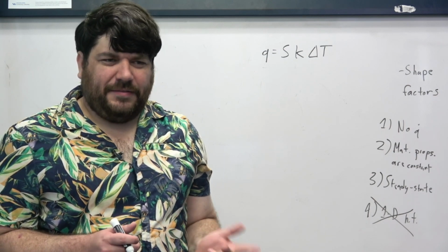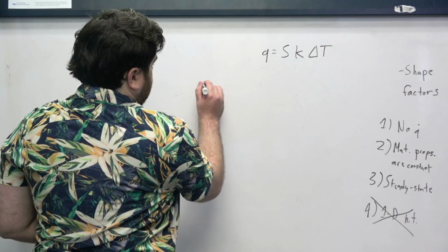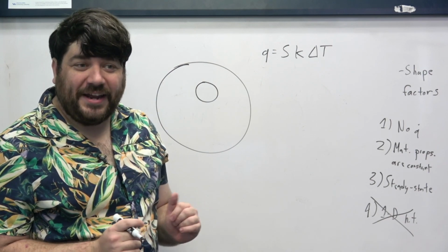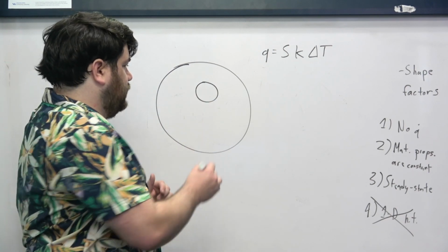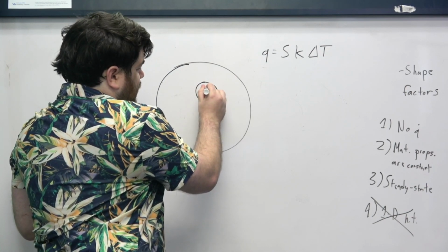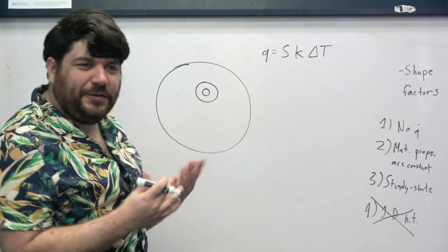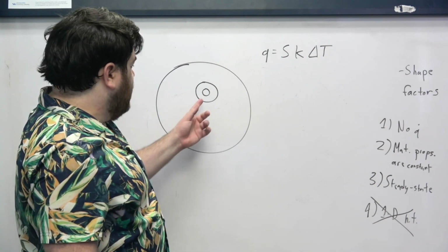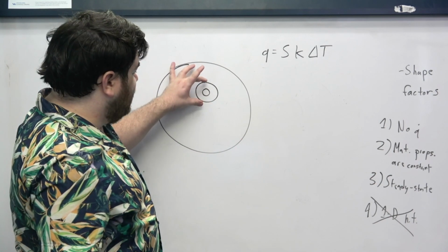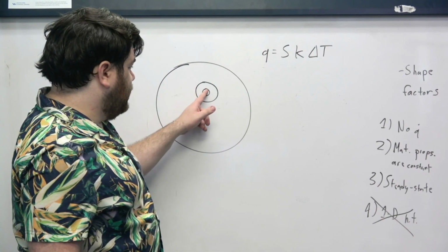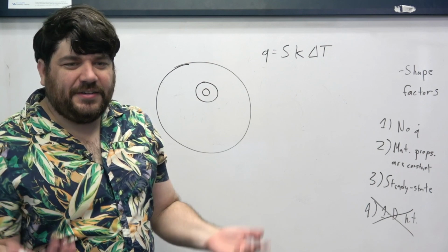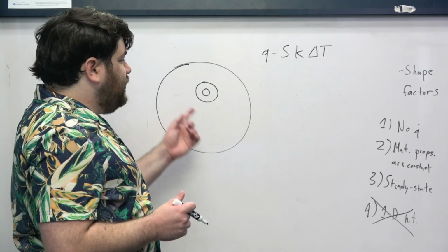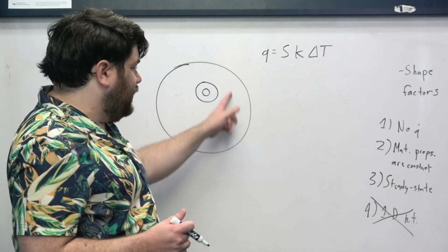Now, if I had a situation where, just like before, I had my non-concentric cylinder, I might ask myself, well, maybe I can model this thing, or even something more complex, so maybe something like this. This, I can assume, behaves a little bit like a thermal circuit described system, right? Maybe in this central region, the heat transfer that's occurring between this cylindrical core all the way to the outside does satisfy the assumptions. And maybe the only thing that doesn't satisfy the assumptions is this thing here on the outside, right?